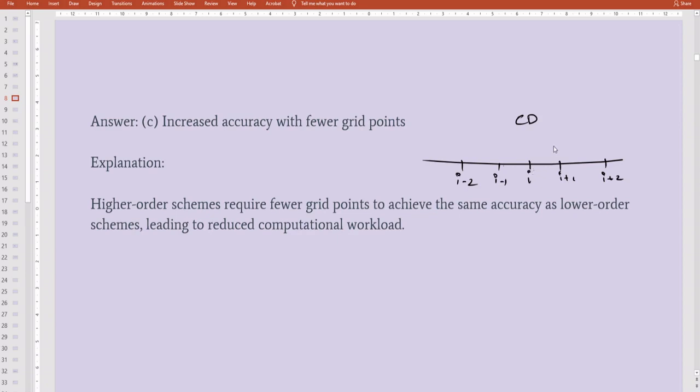So this is the one dimensional case I am showing. To get a decent accuracy in most of the first order cases, the terms in I, I plus 1 and I minus 1, these three terms are used. But to get higher accuracy, we will be using up to 5 grid points in normal conditions in several different schemes.